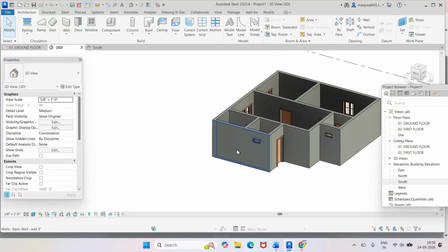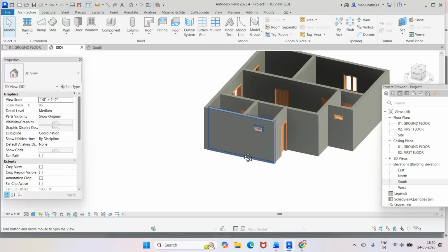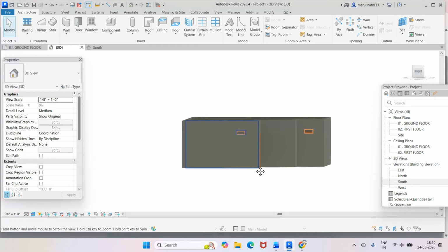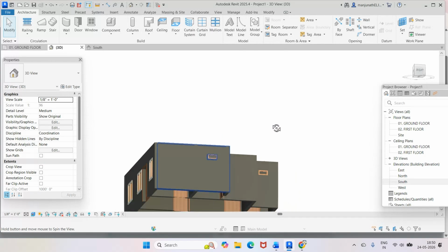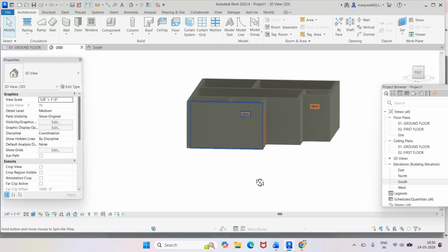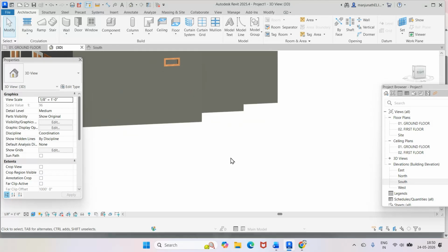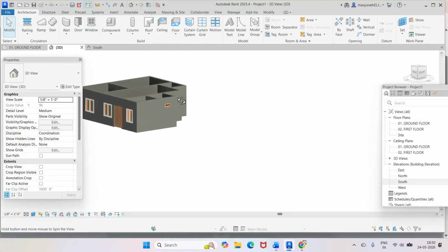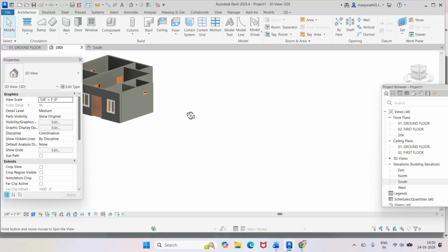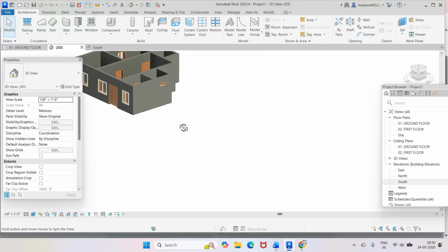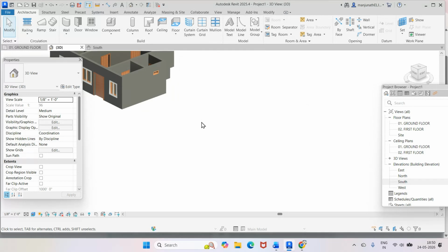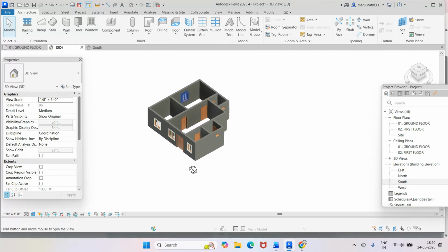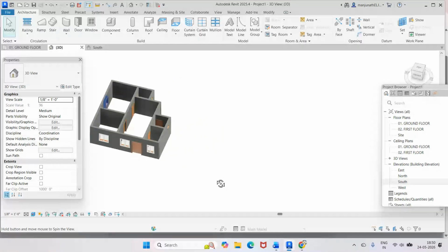Now I'll just press it by holding the shift key. Now I can rotate in whichever direction we want. So this is how I can place the different doors and windows on our plan. If you just come down to this and you just click over and see, these are the things.